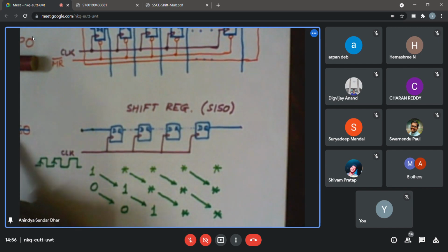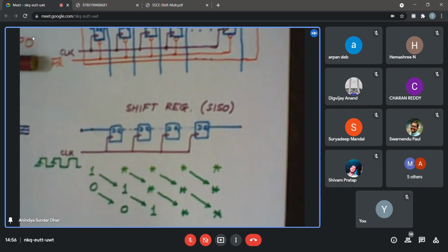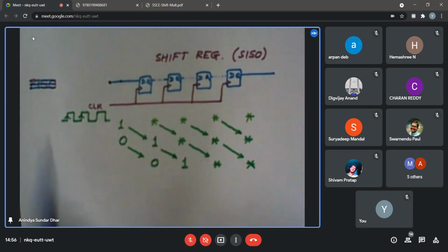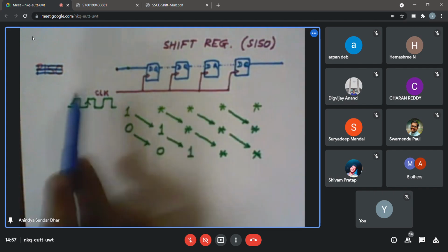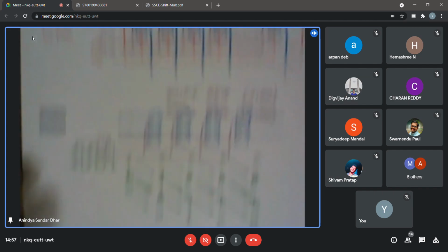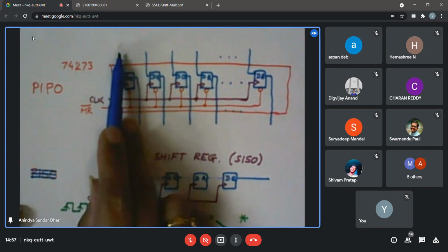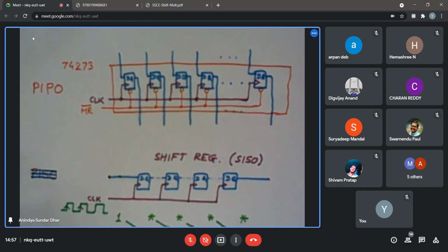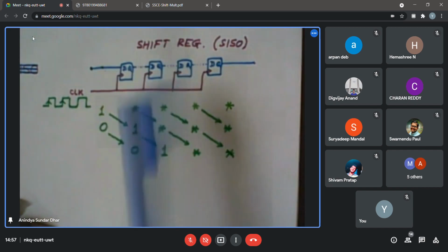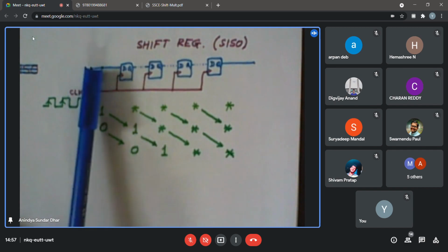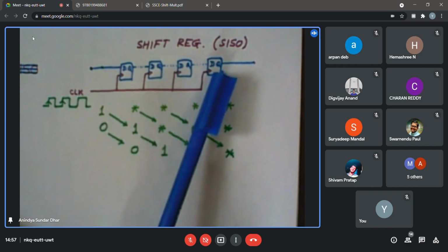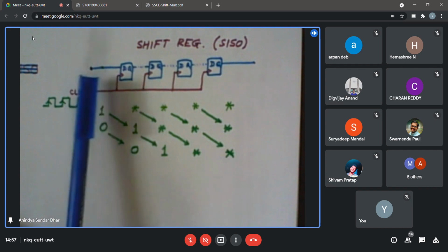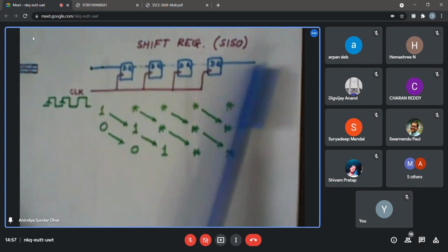Yes, there are. So this is not PISO. I have just cut it out so that there is no confusion. This is called SISO, serial in, serial out. There is no provision of parallel input. Parallel input is the earlier one, parallel input, parallel output, where I can load all the bits concurrently, but here it is not. If I have to populate a 4-bit number, then I have to do it in 4 clock cycles, serially sending the value from here. I will send the LSB first if this side is LSB, then the MSB I will send last, which will be stored over here.